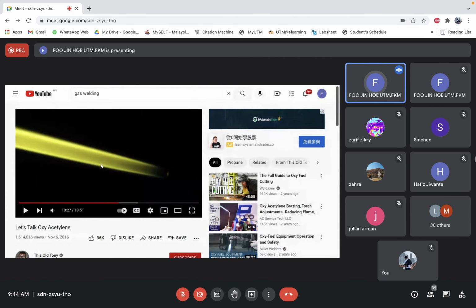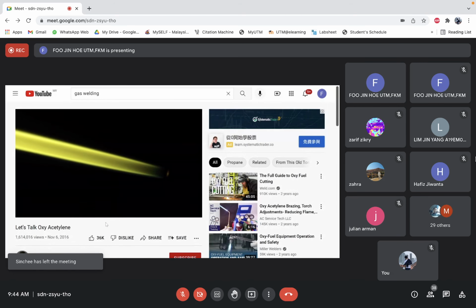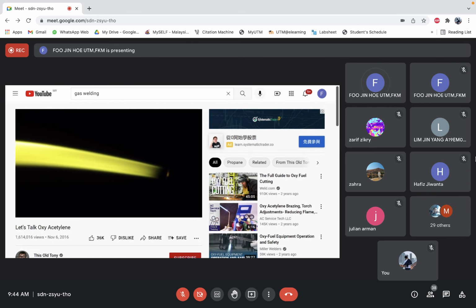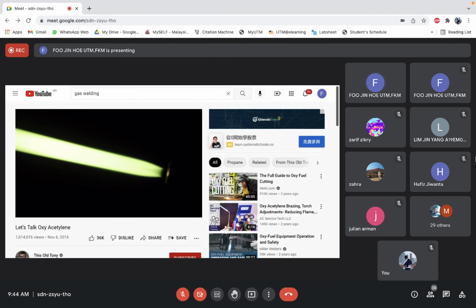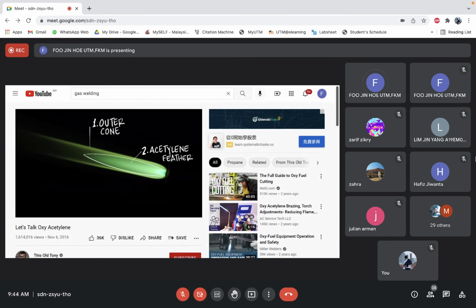Okay, so you can adjust or control the ratio of this acetylene gas flow and the oxygen gas flow that is going to mix in this combustion. Here is the acetylene flame from before, no oxygen, and you're looking through a pair of welding goggles. You're going to start to slowly open the oxygen up, and you may or may not see three flame cones in there: the outer cone, the inner cone, and the smallest one nearest the nozzle.